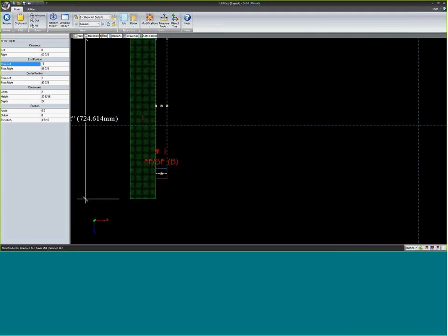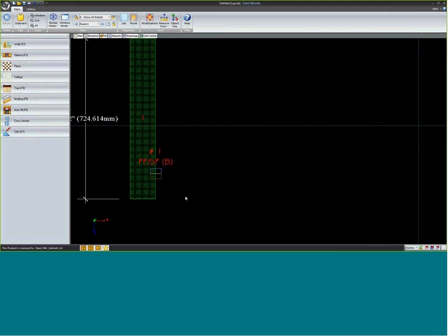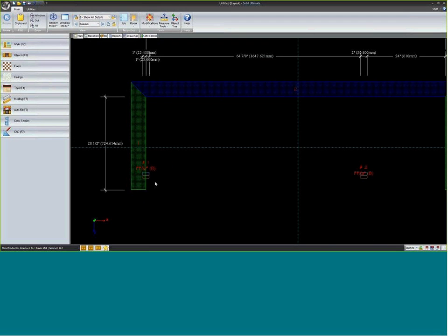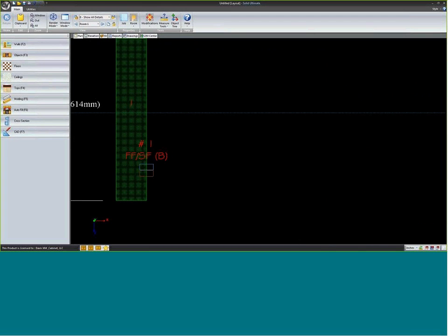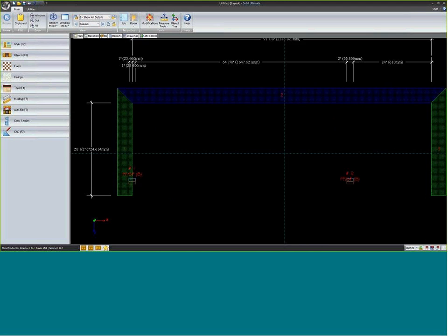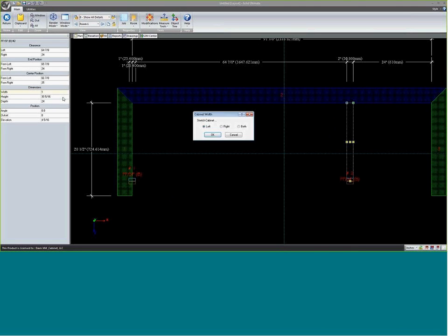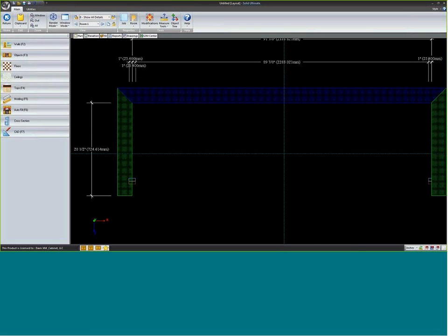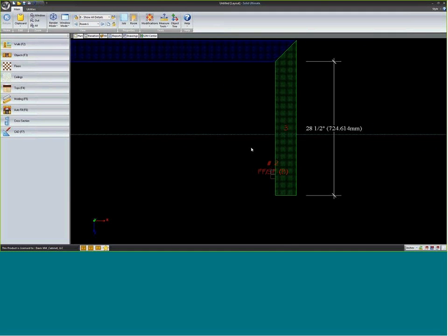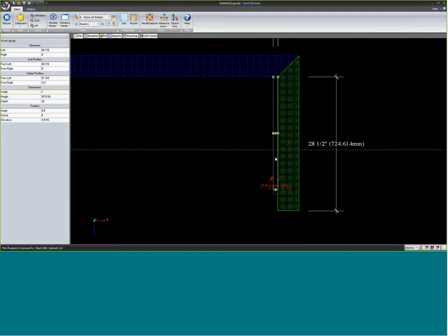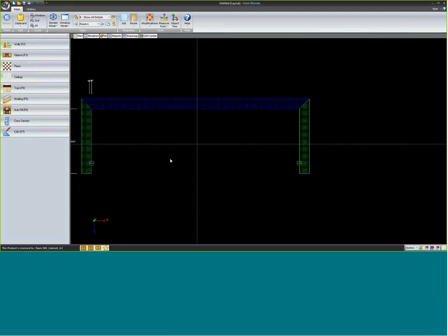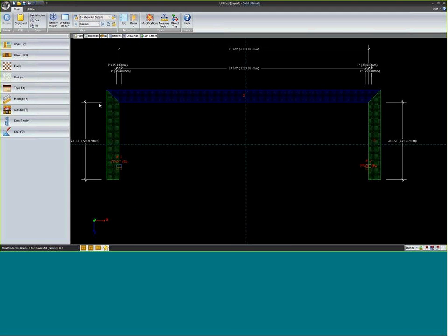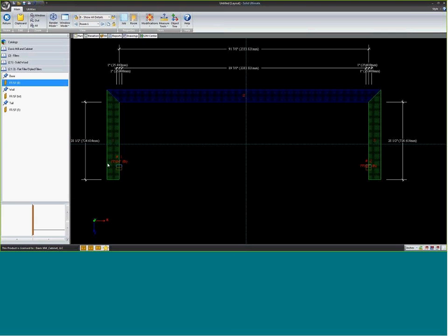But if I do a -1 on there, I've inset the filler into the wall. So now for your rendering it's correct, but also for your pricing it has the correct size, and for manufacturing it has the right size that you really want it to be. Don't just put in a 1-inch filler into the wall like that and expect it to have scribe automatically included in it, because it won't. We're going to build it exactly the size you say on here. So if I set that at 2 and then I say a -1 inset, then this is a scenario where I do place my fillers first, because it's much easier to place those fillers and inset them in the walls,